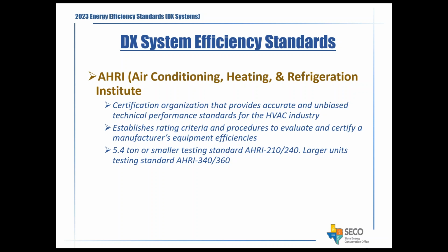standards is AHRI, which stands for Air Conditioning, Heating, and Refrigeration Institute. They are the certification organization that provides accurate and unbiased technical performance standards for the HVAC industry, establishes rating criteria and procedures to evaluate and certify manufacturers' equipment efficiencies, and units that are 5.4 ton or smaller have a testing standard called AHRI 210/240.